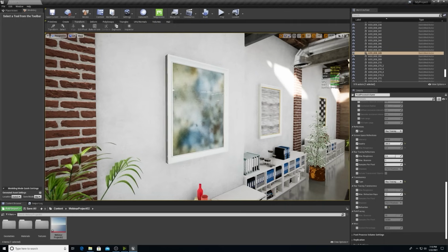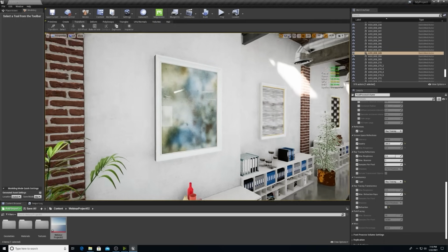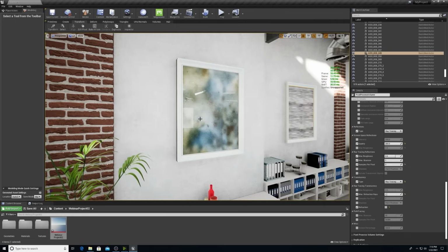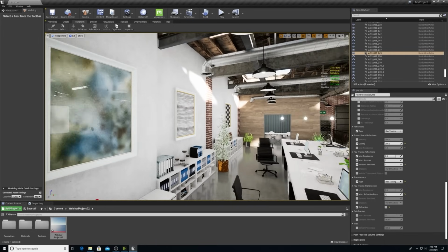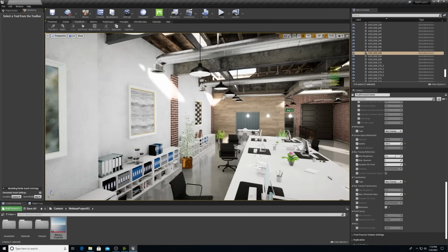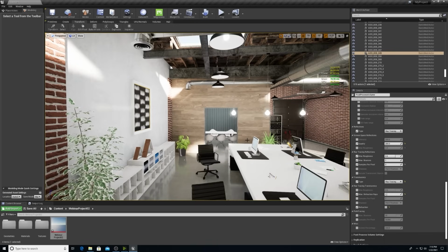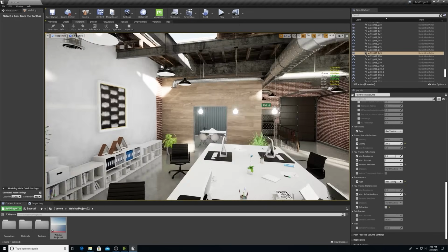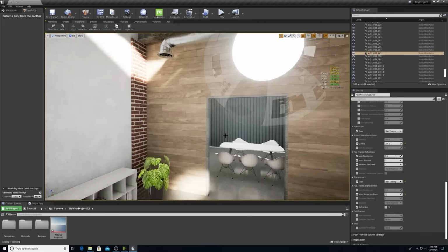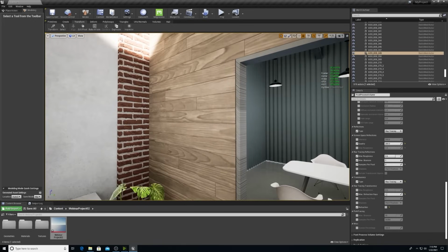So now you'll see that it's nice that some reflections came back in, but it doesn't have that Z fighting black effect. Now you may also notice that the barn doors from the Twinmotion file that Martin set up did not come in. At the moment, skeletal meshes and animators from Twinmotion cannot be imported. Without this, you can see that it exposed the door frame that did not have a UVW map set up.